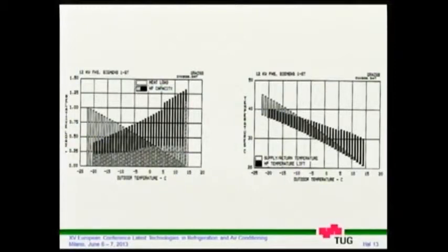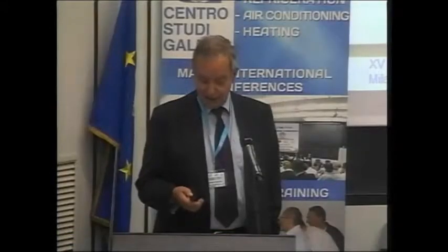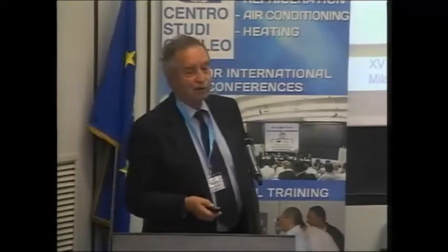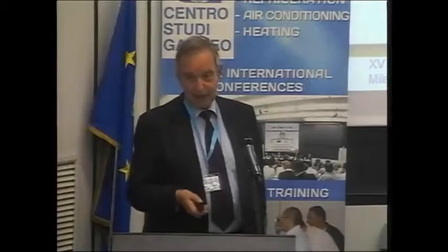That means you have, of course, on-off cycling losses, and you have these excess temperatures, which cost a lot in COP. If you want to improve this, you can do it by introducing a buffer storage. That means decoupling the heat delivery by the heat pump and the heat use by the distribution system.